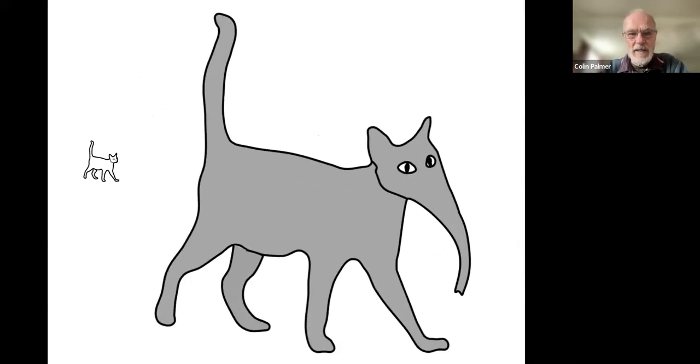So let's think about it this way. Here's a cat, slender legs, long thin tail, and a very good mouser. Now imagine we scaled up this cat hugely and made a cataphant out of it. Not such a good mouser with long slender legs. Well, behavior aside, that creature is impossible because those legs would not be strong enough to take its weight, because the strength of the legs is more or less proportional to the cross-section of the bones, which is an area thing.